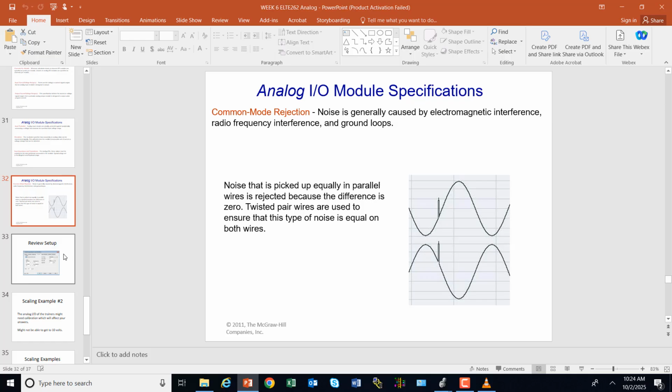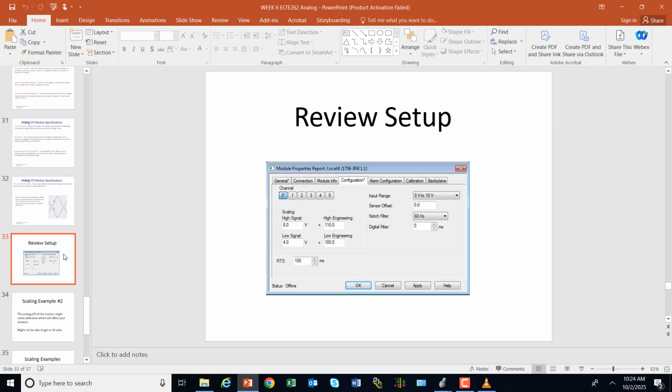So when we go and set up our cards, you can go through all these connections. I got a little item here at the start of the lab that just has you go and set up an input and output card. Be sure that your input's reading and that your analog gauge is moving, pushing the output. But the main thing to do right here is to understand the configuration.